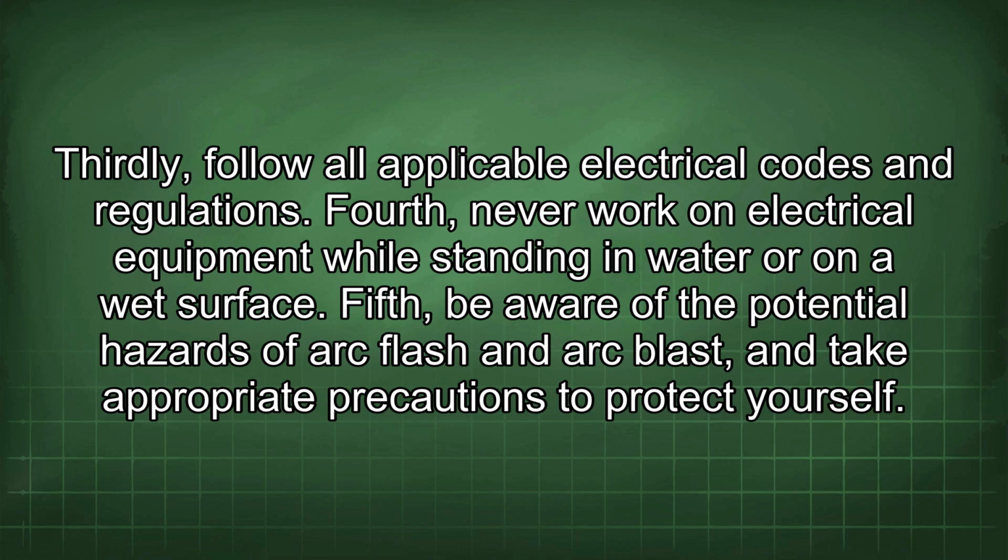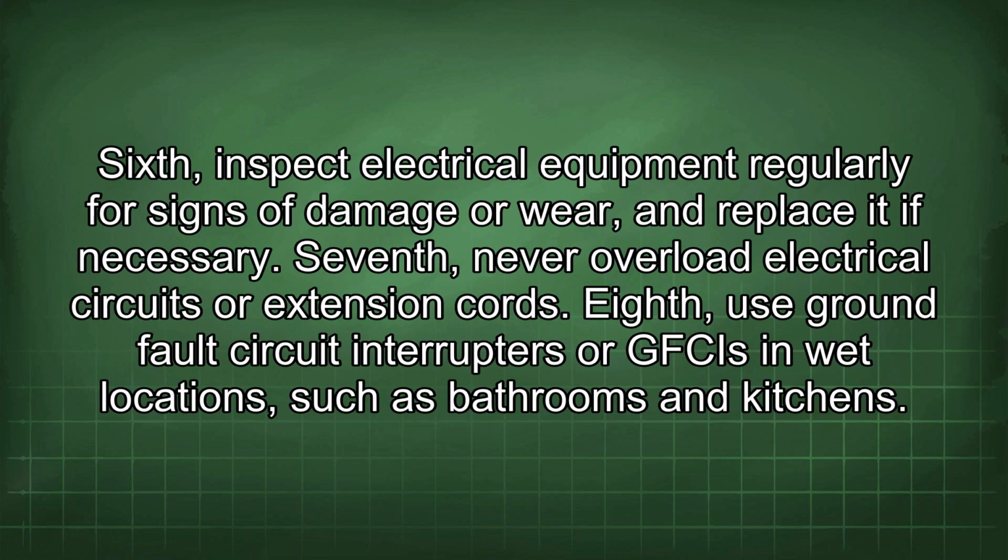Fourth, never work on electrical equipment while standing in water or on a wet surface. Fifth, be aware of the potential hazards of arc flash and arc blast and take appropriate precautions to protect yourself. Sixth, inspect electrical equipment regularly for signs of damage or wear, and replace it if necessary. Seventh, never overload electrical circuits or extension cords.